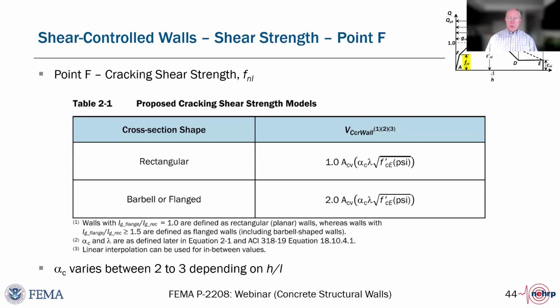Very good. When you were talking about the conforming versus non-conforming, you said that inadequate lap splices weren't explicitly updated, and I have had a couple of questions about that. One was, how would ASCE 41-23 classify a flexure-controlled wall that meets the conforming detailing and has adequate lap splices near a critical section? Is it still treated as conforming then or not? If it does have adequate, was the question? Yeah, adequate. The question is if it's at a critical section, the new building approach might be different.